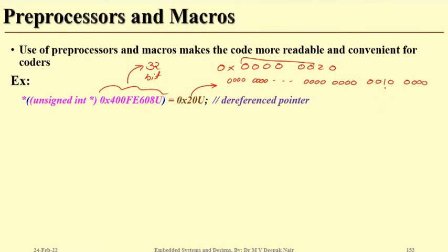Now you understand why we are entering 1 here. Why bit number 5? So bits 0, 1, 2, 3, 4, 5. Now does it make any sense why we are making pin number 5 a 1? You have to enable port F.